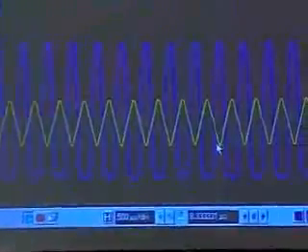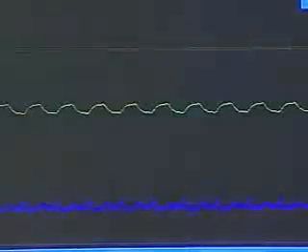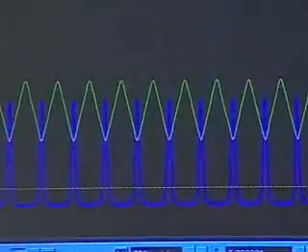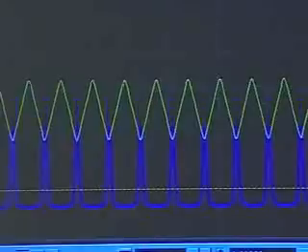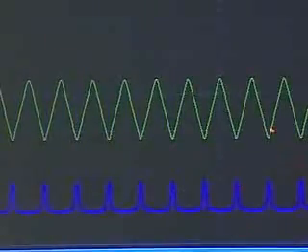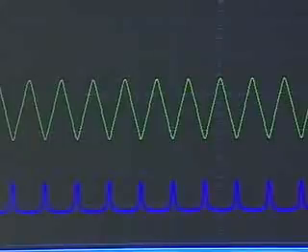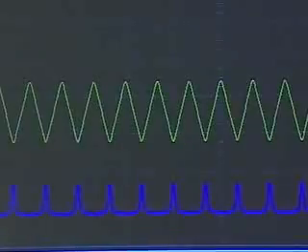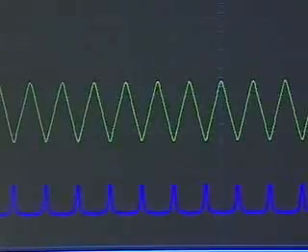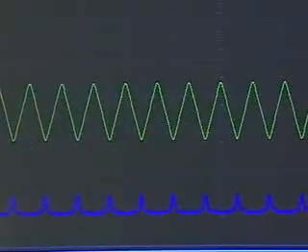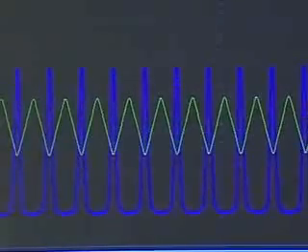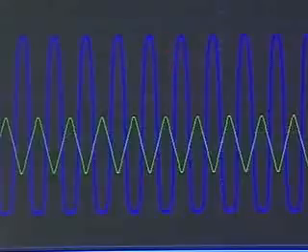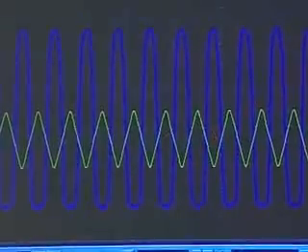So you'll notice the input going higher and higher. I'm going to pull the trigger point down. There you go. So notice that as I boost up my input even higher, the output is a really small image of what the right input should be. The right answer here, of course, is that I apply some right amount of offset to boost up the input into the right regime so that the output is seen to be some amplified version of this input.